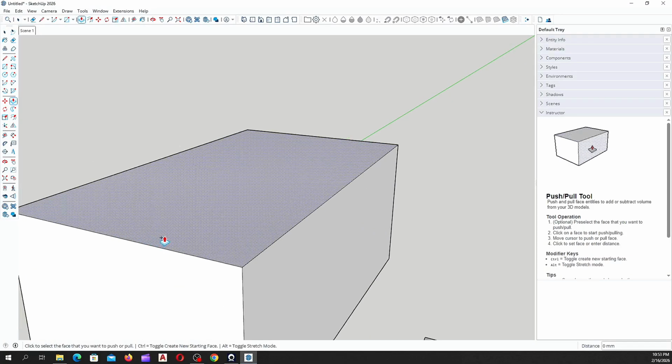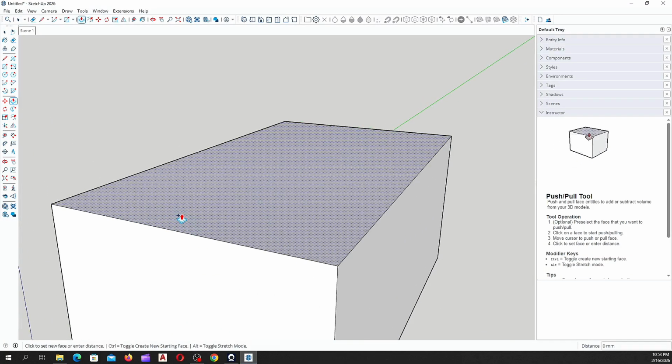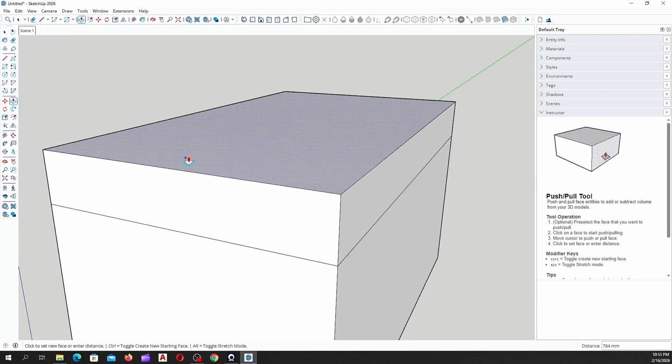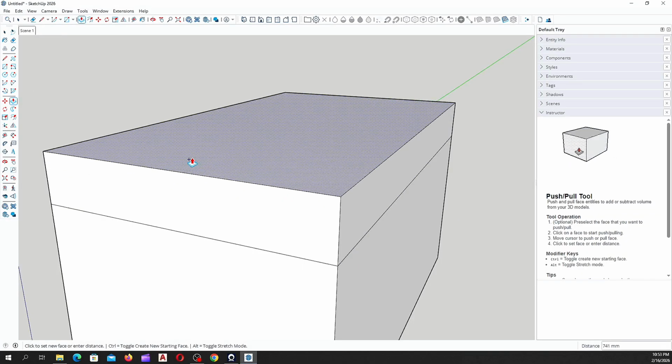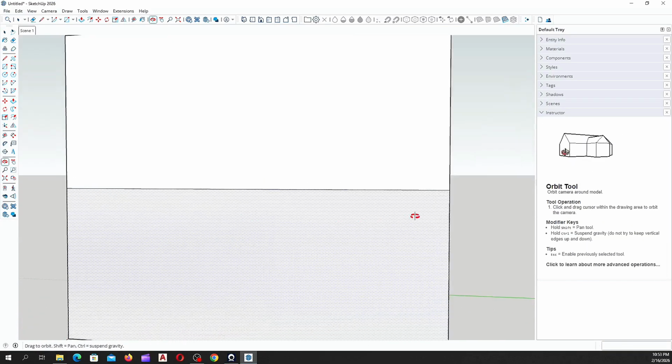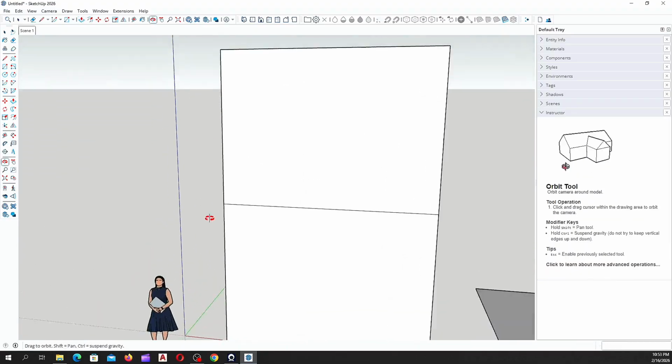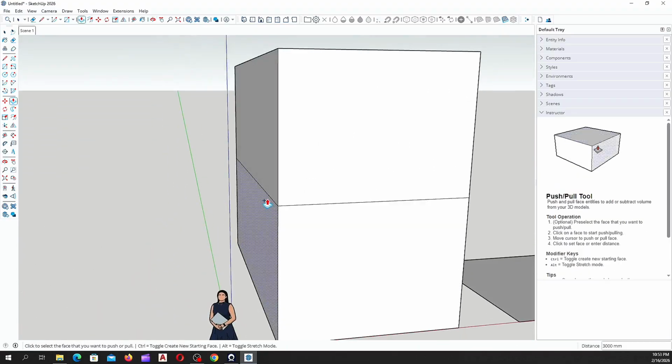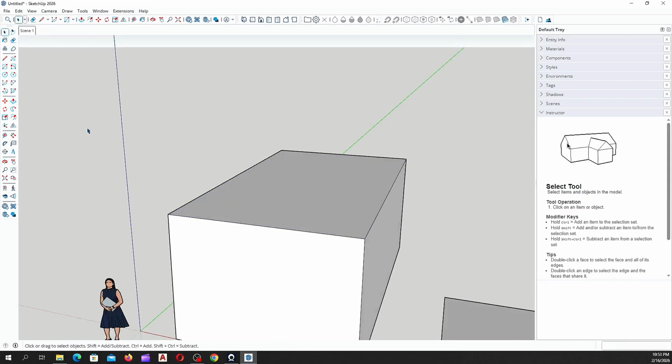It means it's going to give you a demarcation between your initial surface and the new pushed surface. So let me enter the value 3000 again. You see, we have a demarcation between these two surfaces, provided you activate the plus sign by hitting your Control key on your keyboard. Okay, let me hit Ctrl Z. Okay, so next.